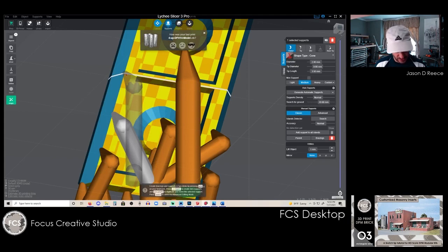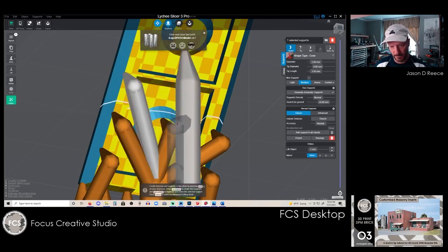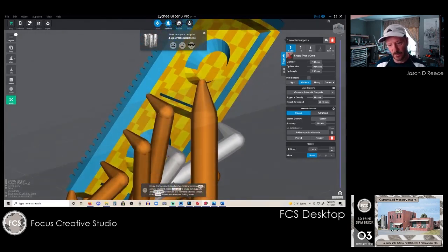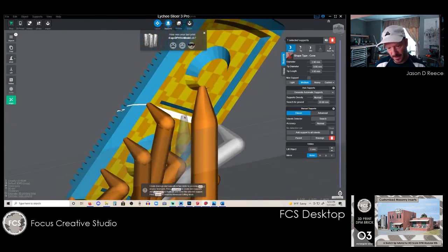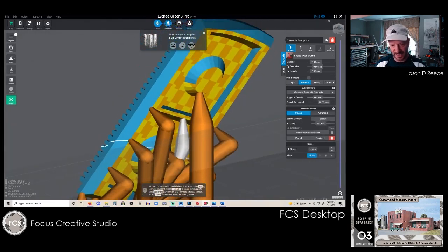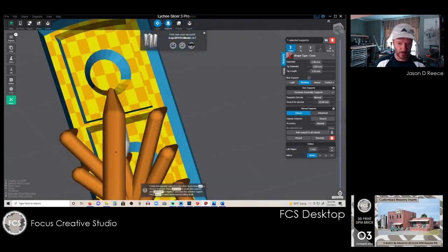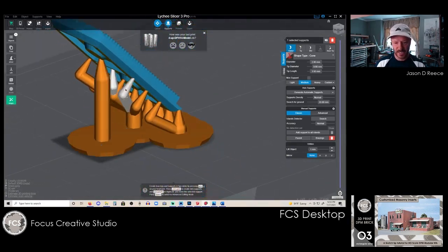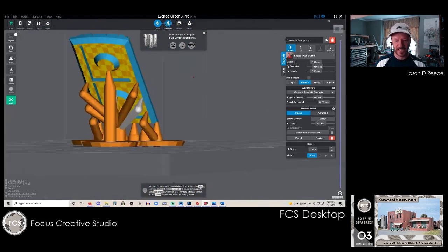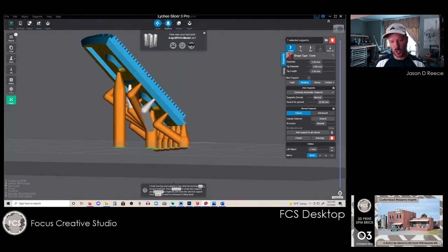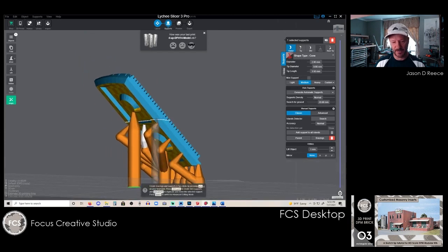And so now with these, I'm gonna do these all the same. I'm gonna use that anchor point right there. Alt, drop it down. Let's go ahead and drop one out here at this corner. Alt, just drop it in there. And I'm gonna drop one right here in the middle of that piece, right there. Alt, I'm just gonna tack it to that. So support on top of support, that'll print just fine. So again, see, don't have a big mess on the bottom, keeping my supports clean, and these will all print and hold on to this model and keep everything aligned beautifully.